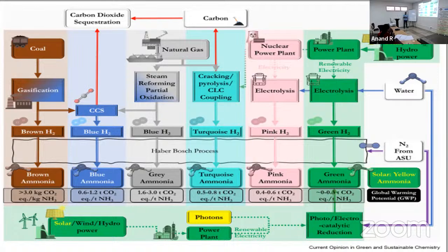Similarly, if my PV system is 1 kilometer away, I am transporting from there to here. In that energy transmission, lots of losses are there. We have to consider that also. So here I need 1 kilowatt hour, which means there I have to produce 1.2 or 1.3 kilowatt hour. So I have to consider that CO2 equivalent. Similarly, this is for the emission aspect. From here to here, how much CO2 is coming out, that is displayed here.